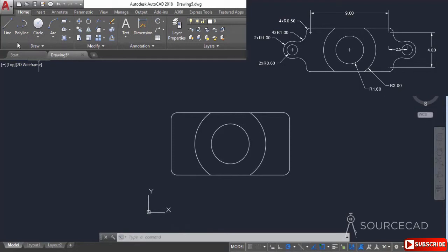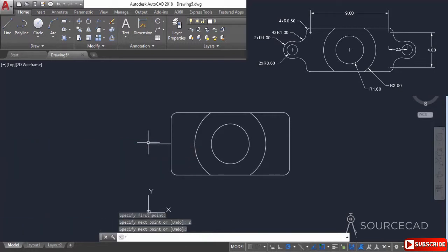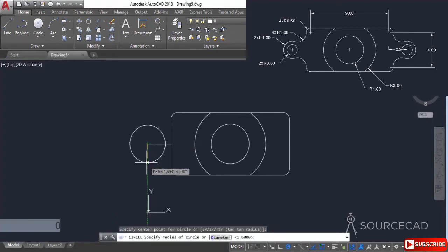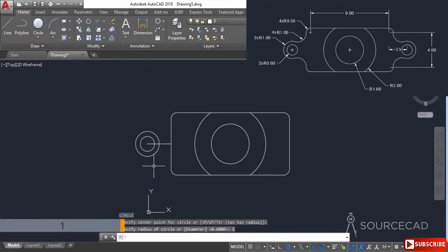Here we need to add another line with length of 2 units. So I'll click on this midpoint and I'll enter a length of 2 unit and press enter. Press enter again to exit this command. Now we need to go to circle tool and click on this endpoint and make a circle with radius of 0.6 unit. Press enter again, and this time again go to the same point and make another circle with radius of 1 unit and press enter.